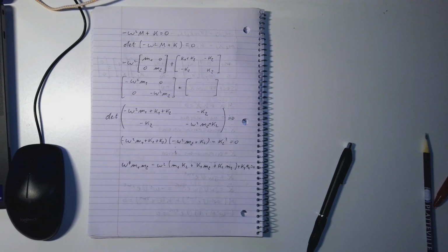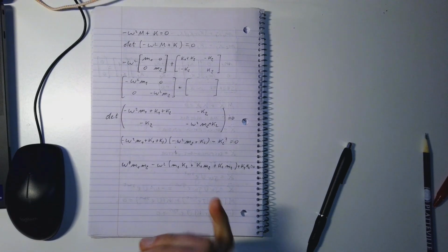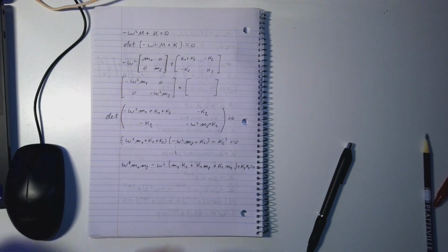because these are coupled. And we will see, I don't know if today we will have the chance, but for sure next time, from the final solution, that in the displacement of the first mass you will see both omega 1 and omega 2, and in the displacement of the second mass you will see both omega 1 and omega 2. Makes sense?